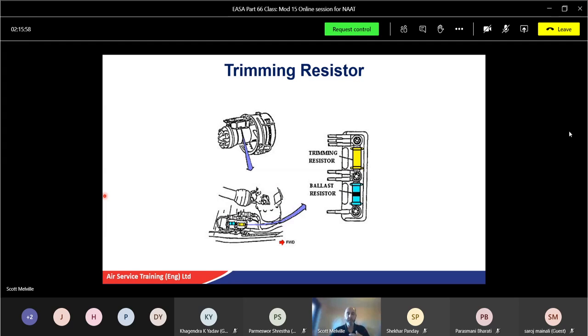Okay, so different resistance, each system will affect the calibration. So it trims for calibration of control to help control the fuel flow. So to compensate for small variance in system resistance, they fit to either the engine or the airframe thermometry system, and sometimes both. One of the trim resistors using the airframe will be adjustable to allow for small variations to be compensated for. So it's the material properties of the components, the harnesses, the connection, and even if you torque tighten it too much or not enough, that can change the resistance properties as well.